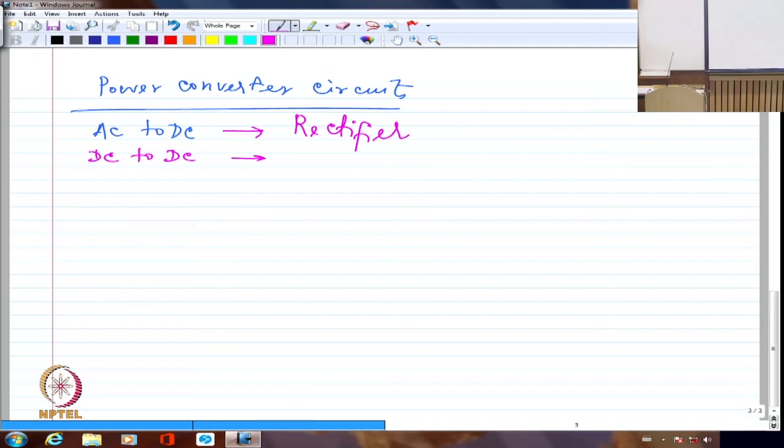What I am trying to say is, if let us say originally the voltage is 20 volts, right? I want only 10 volts on an average basis. I cannot make 20 to 10, obviously. If I have to do that, I have to use two resistors, say 10 ohms each, drop off half the voltage in 10 ohm, the other 10 ohm will have 10 volts. I don't want to do that because it is lossy.